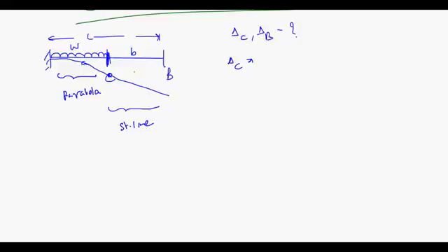What is the value from our standard case? Is it WL to the power 4 upon 8EI? Isn't it? WL to the power 4 upon 8EI. Is it WL cube upon 6EI? What is theta C? Is it WL cube upon 6EI? Okay, so you know these values.